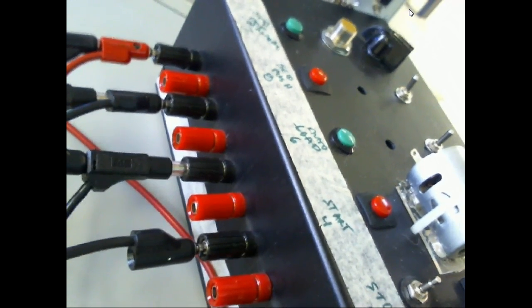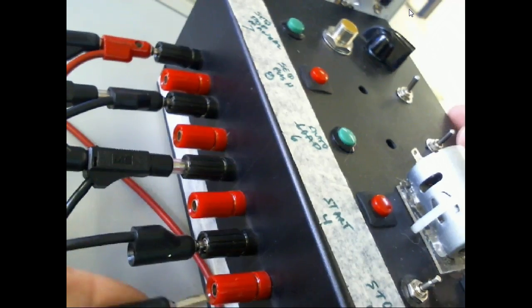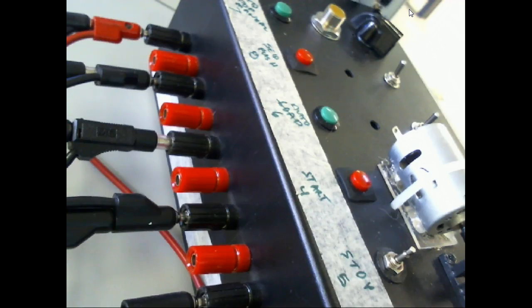And then once I've got all these things set up, depending on how many I need, you see, that's all I'm doing. Okay, so what I've done is I've set up a common for my input, my actual switches, and I'm using a positive common for my switches, and I'm using a negative common for the PLC. So my PLC input is set up to what? Sink, and my switches are set up to source.